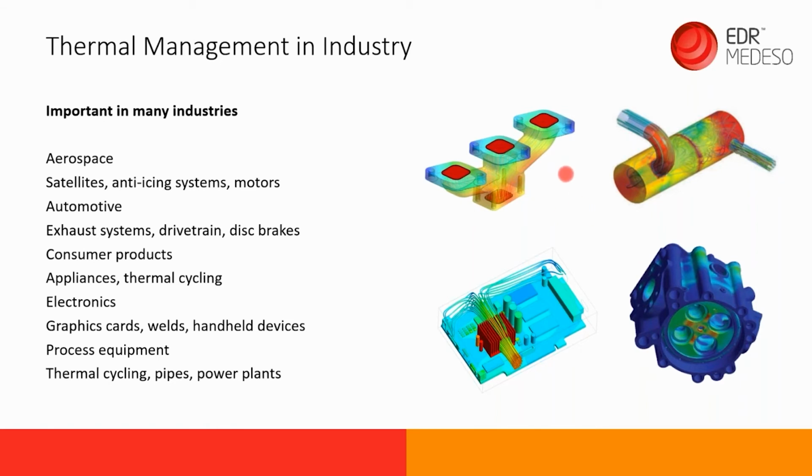In these cases, the reason you do CHT is most often because you're trying to mitigate or avoid mechanical impacts of thermal mismanagement. If your temperatures aren't controlled, then you get fatigue, cracking, and this kind of thing. So oftentimes we do the CFD with the end game result of performing some sort of structural analysis.